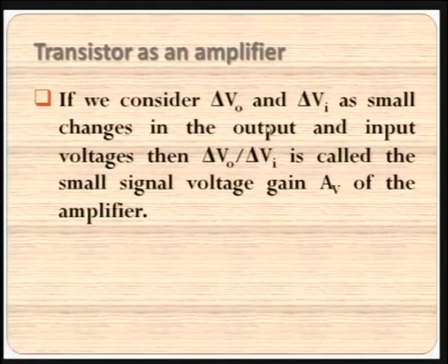We will do that analysis in future lectures, but right now, as we are going ahead with circuits confined only to the common emitter mode, let us keep this point in mind. The amplifier has a phase reversal. The input and output will have a phase reversal of 180 degrees. This is in short called out of phase.